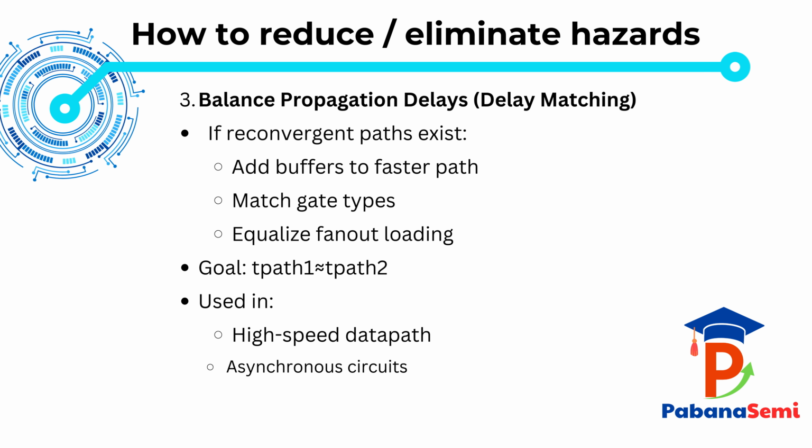This technique is commonly used in high-speed data path designs, asynchronous circuits, and critical timing paths in ASIC implementations. However, in large digital systems, delay matching alone is not always sufficient, which is why synchronous design is still the safest approach.